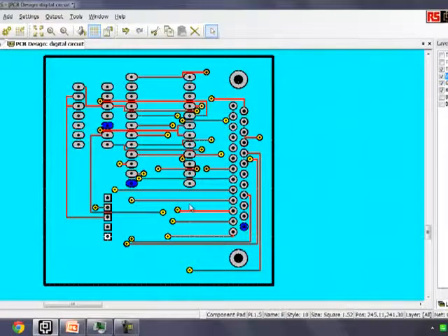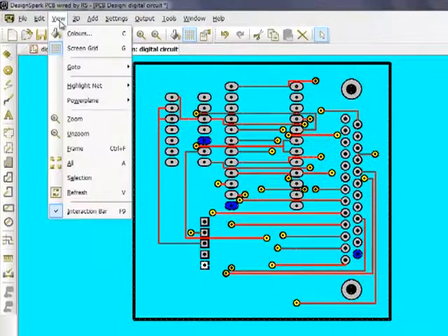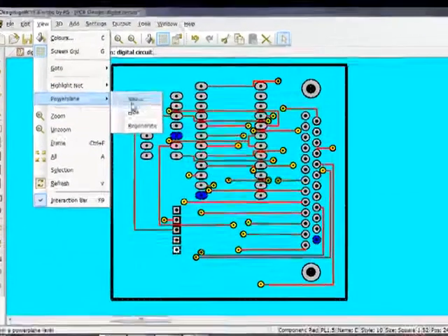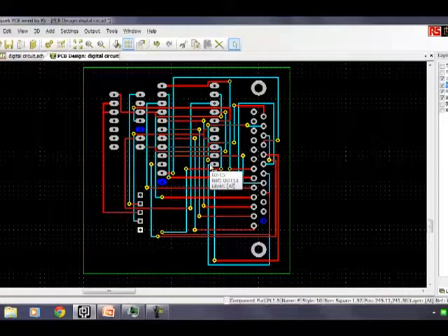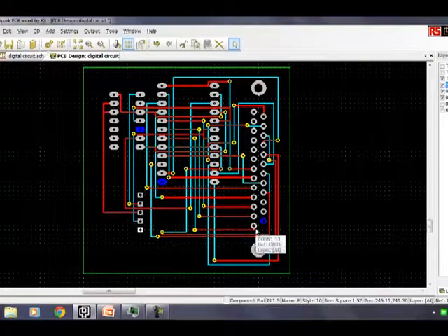So just to recap what we've done: by using the ground plane and the VCC plane, we've been able to provide layers within the board, a complete sheet of copper sandwiched within the board, and connect straight down into it by drilling down through the board and tagging on to those layers. This has allowed us to reduce the number of PCB traces we physically needed on the board. It also potentially gives us some advantages regarding grounding,